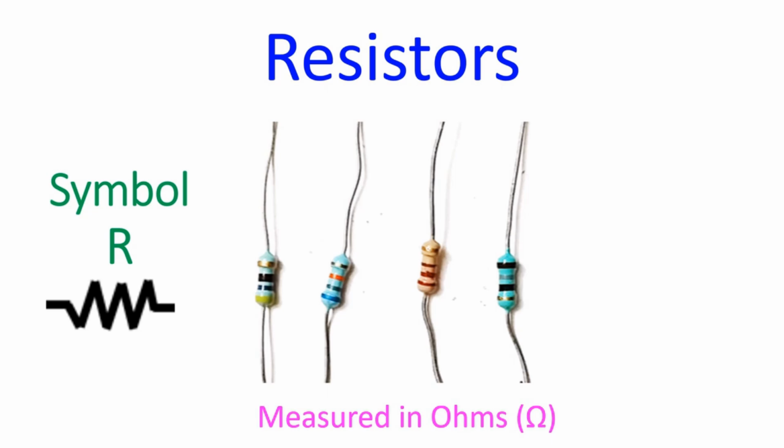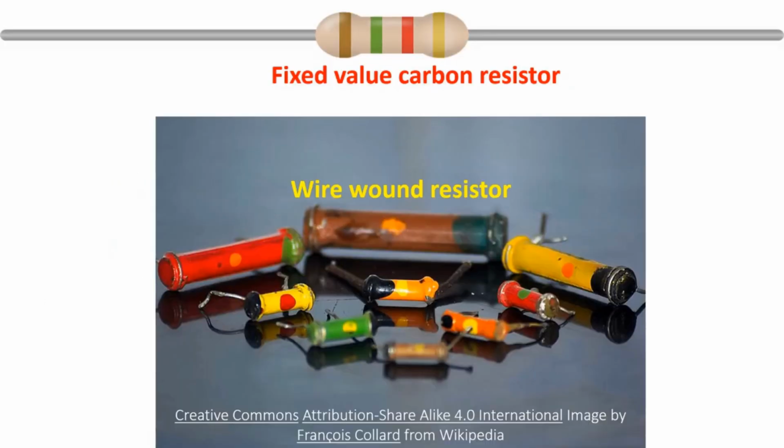They can also be used to provide a voltage using a voltage divider circuit of 2 or more resistors, as in case of providing a bias for the base terminal of a transistor. Transistors are semiconductor devices with base, emitter and collector terminals widely used in electronic circuits. Two important types of resistors are wire-wound resistors and carbon resistors. The resistors illustrated earlier are carbon film resistors, the resistance value of which depends on the amount of carbon present in them.